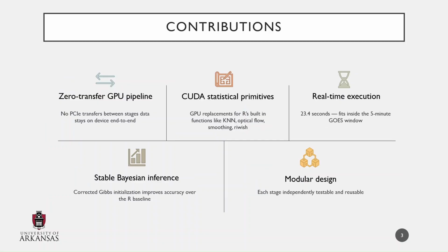Our 5 core contributions are: first, we present a zero-transfer GPU pipeline, meaning all data stays on the GPU device throughout the entire computation. There are no PCIe transfers between processing stages and no round trips to the CPU memory. This is architecturally significant, and I'll explain why shortly.